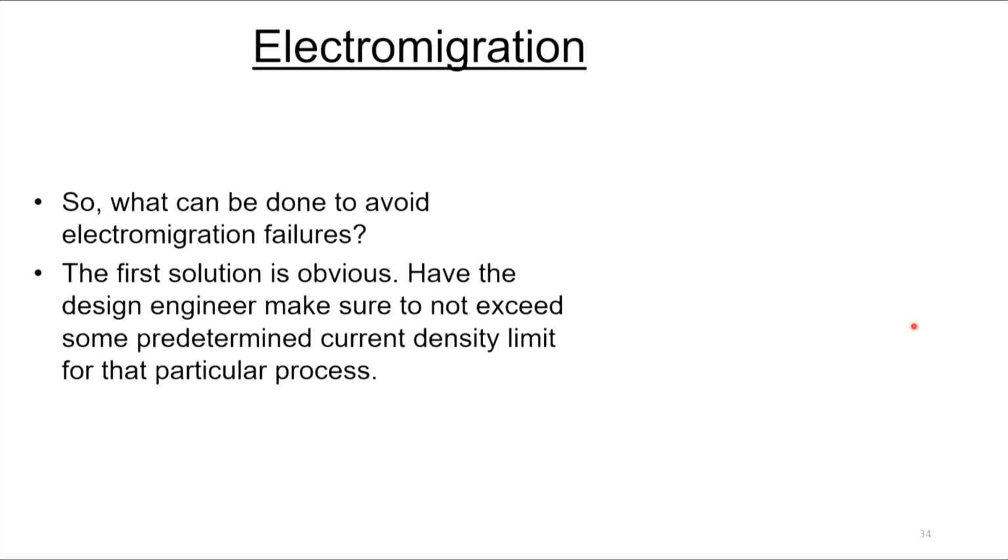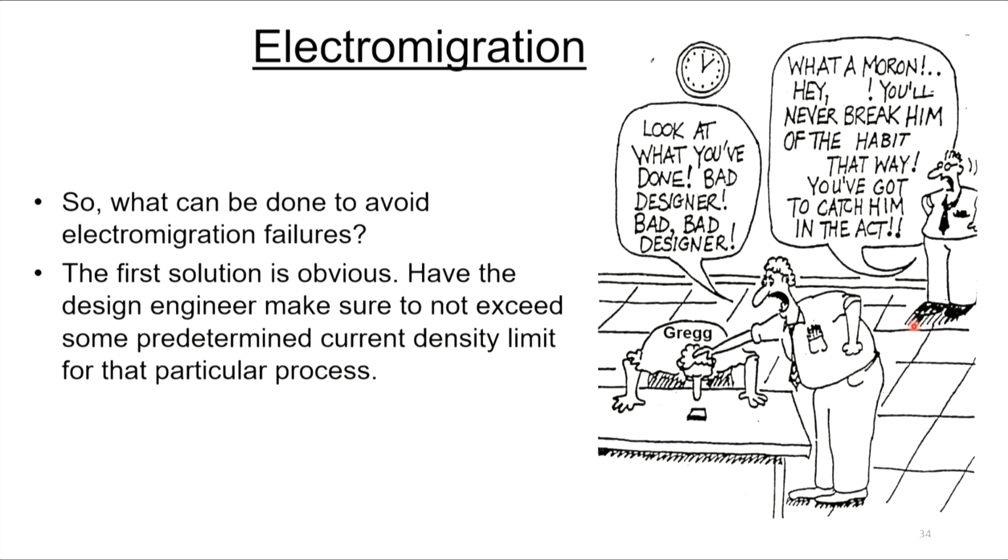So what can be done to avoid electromigration failures? The first solution is obvious. Have the design engineer make sure not to exceed some predetermined current density limit for that particular process.